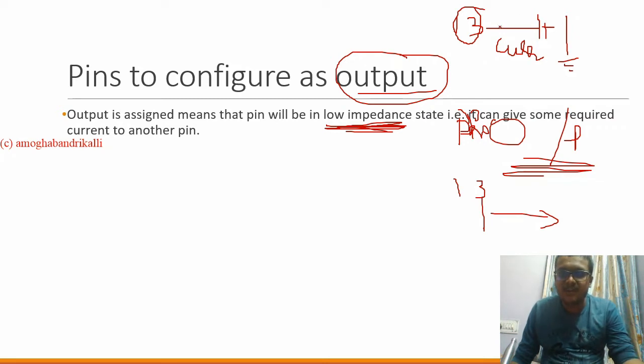In order to avoid it, we are going to connect a resistor in between the output terminals and the Arduino pins, or it can be any sort of microcontroller pins. We are going to connect a resistor in between. The resistor value will range from 470 ohm to 1k.